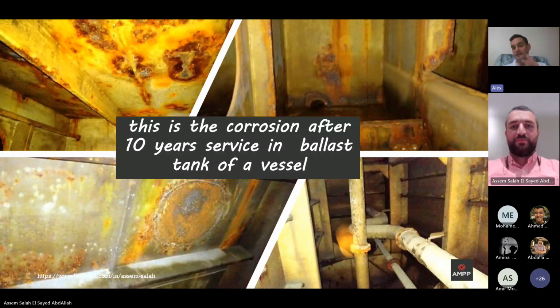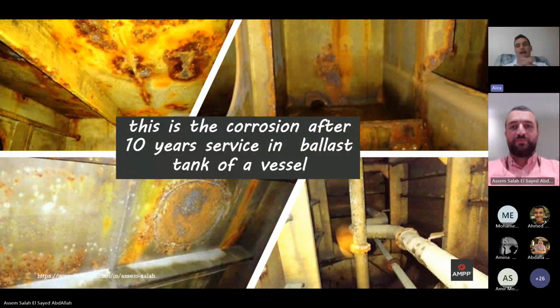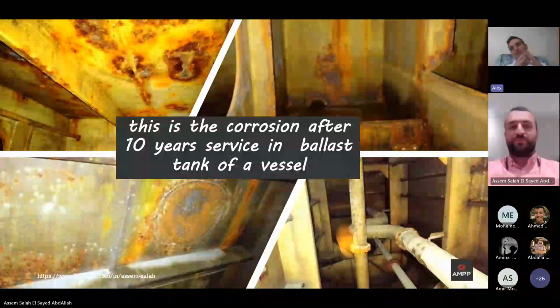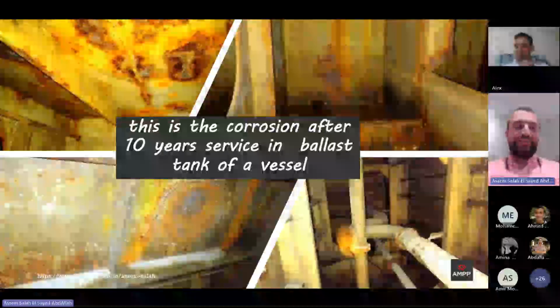And after 10 years, I observed this vessel and noted that the level of corrosion was something like 10 or 20% of corroded spots. These photos just demonstrate the worst places. And the ship owner of this vessel decided to make just water jetting, small water jetting, not water blasting, I would say, 500 kilograms. Not blasting, because you didn't have a surface profile.